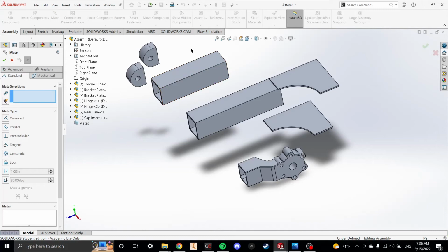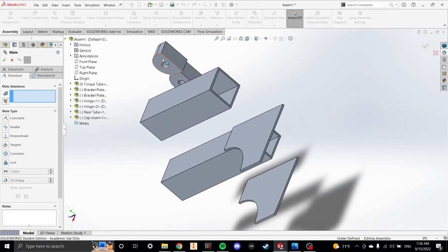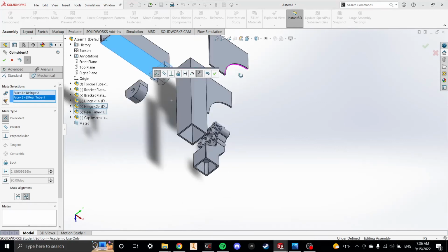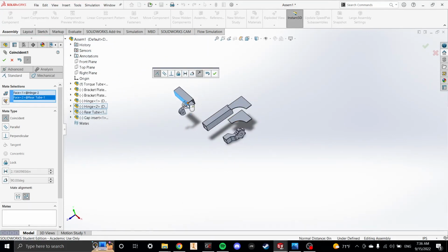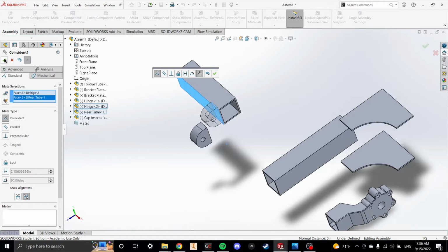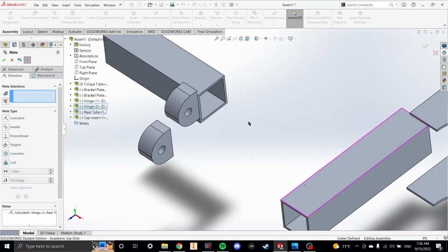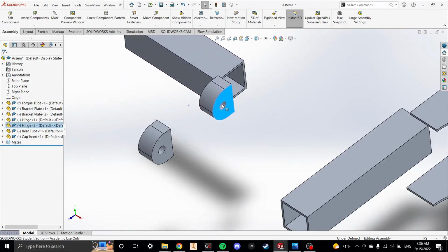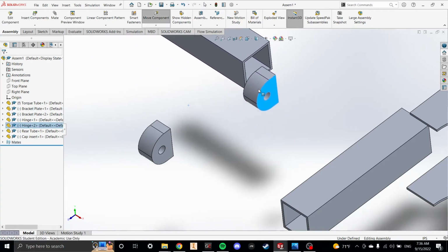And so as we all know, this is the back. So let's start with putting the hinges on. You can take this face and adhere it to this face, and you can see they're going to go one-to-one. However, with most constraints, you're going to need more than one to make them work, because as you can see, with just a face-to-face constraint, the CAD software doesn't know where the constraint is. All it knows is those faces have to be tangential.